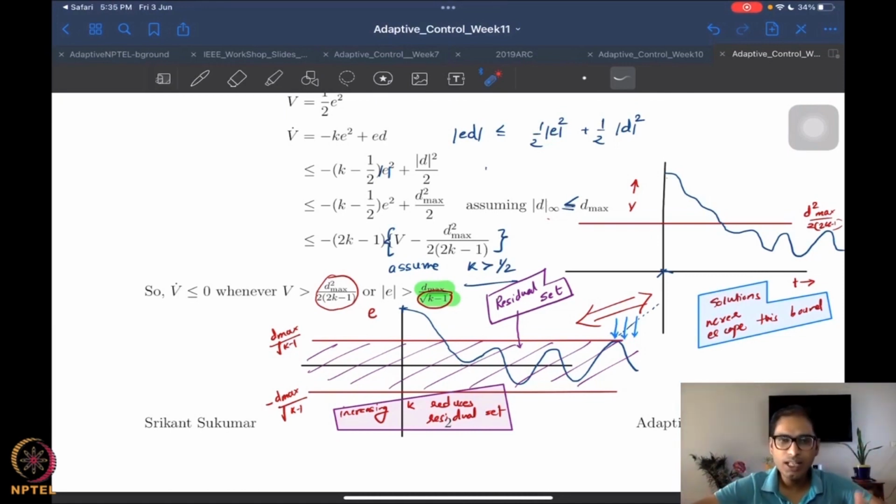So that you can get the performance of your real system, for example, the satellite, to within the necessary performance bound that you want. So this is one of the big powers of the Lyapunov method, that as soon as you make a control design using a strict Lyapunov function, disturbance robustness comes for free. You do not have to do this analysis at all. It's for free because you had a strict Lyapunov function.